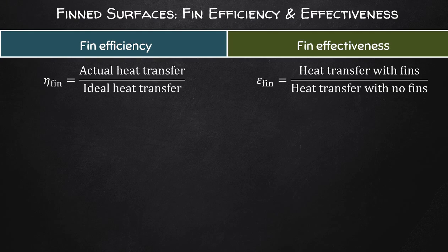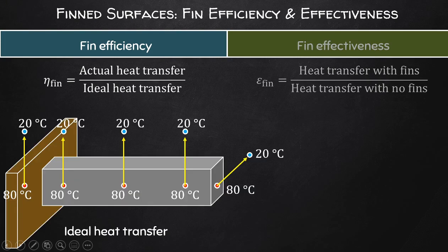There are heuristics that we use where we say, well, we will cut off efficiency at no less than 60%, where most fins are designed to operate at 90% efficiency. How effective should the fin be? Should it be 5-fold? Should it be 10-fold more heat transfer than in the case with no fins? There are heuristics that you can consider as rules of thumb, and use these not as a rule, but just as a guideline.